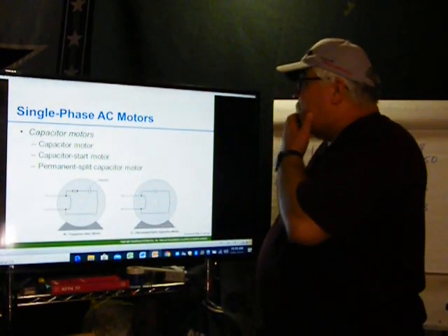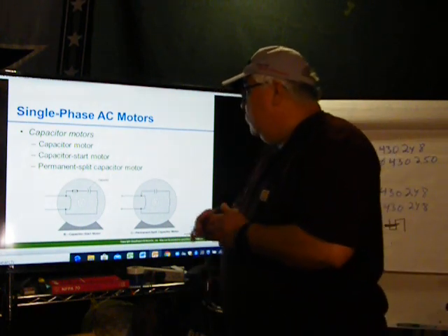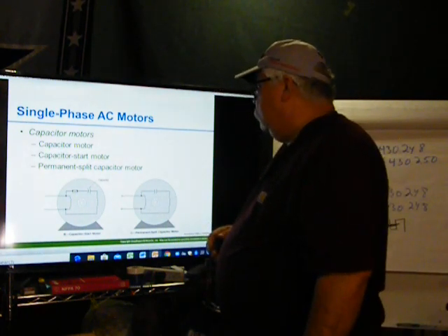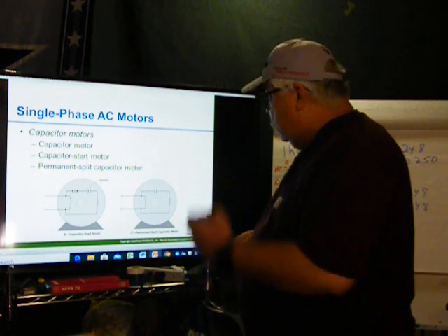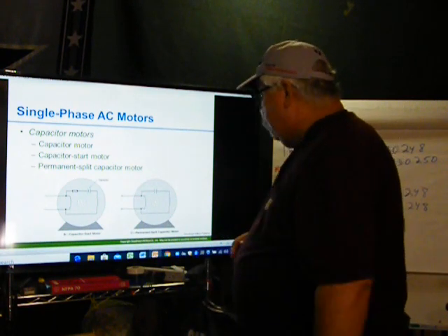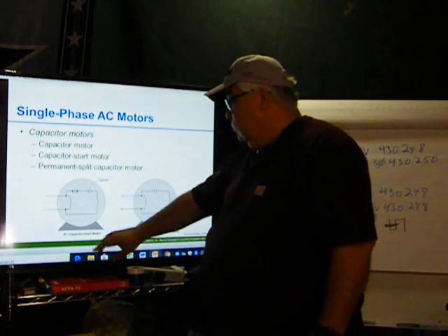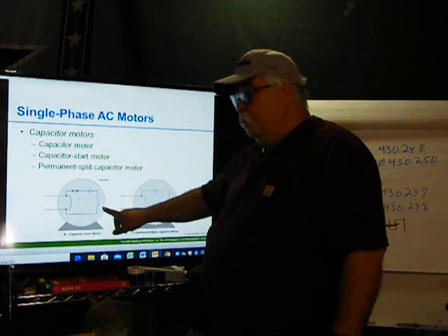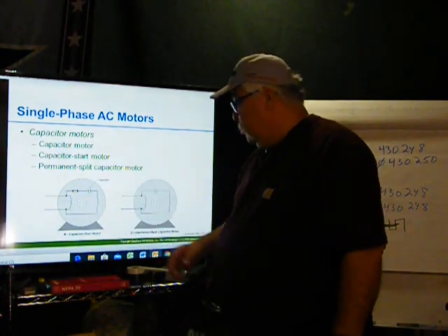Single phase AC motors, capacitor motors. You have a capacitor start motor, and then a permanent split capacitor. So a capacitor start motor is you have a capacitor that helps start the motor, and then once the motor starts, the switch opens up and it takes the capacitor out of it.